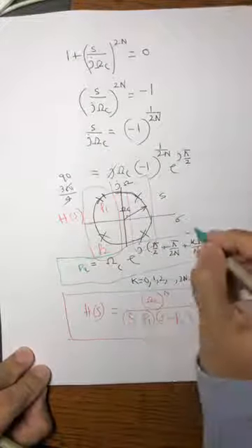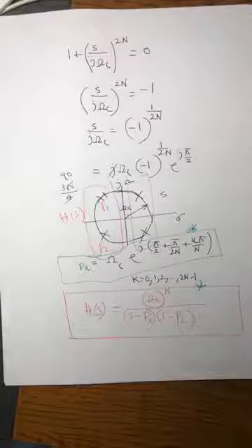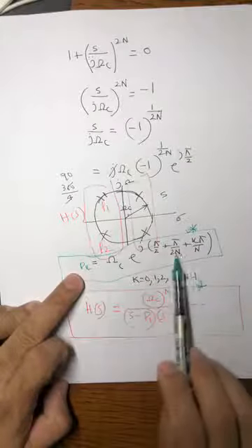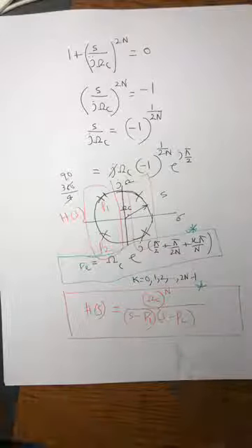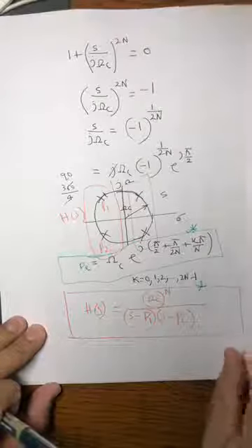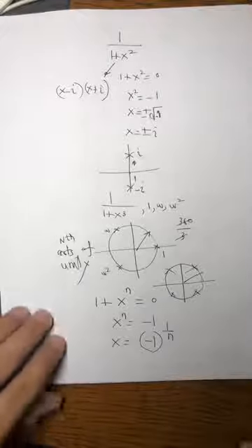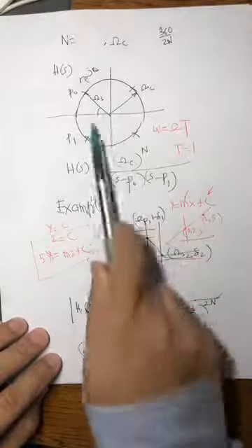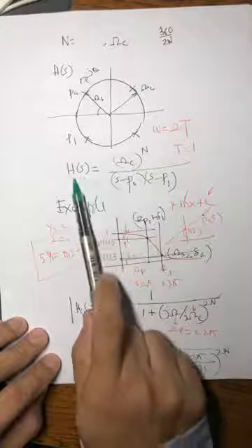So you need to remember this formula, and you need to remember this formula. So you can solve almost any question in filter design, that if you know that these are the locations of poles, obviously you have to find N and omega c, and this is how you write it. And then you combine, you can use binomial expansion, so partial fractions, and then you basically solve it. So we said, okay, if there are only two, then these are the two poles, and this is the expression for H(s).